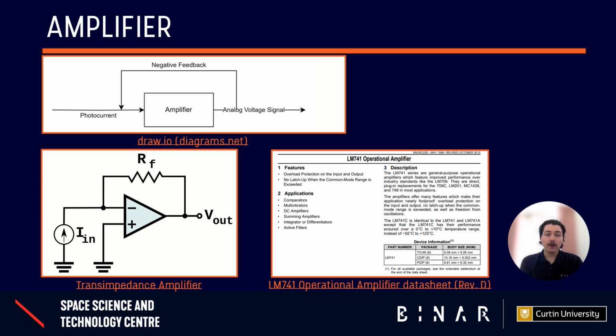So looking for an operational amplifier, we picked a tried and true LM741 operational amplifier, which is a quarter century old. The reason why we picked this operational amplifier is that it's so old that it has models created around it in all simulation software, so that if you wanted to simulate our circuit, you get an accurate simulation based on the LM741 operational amplifier.